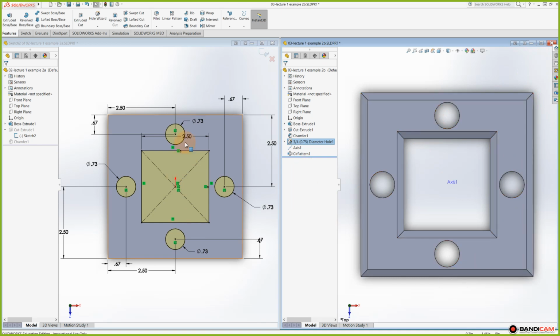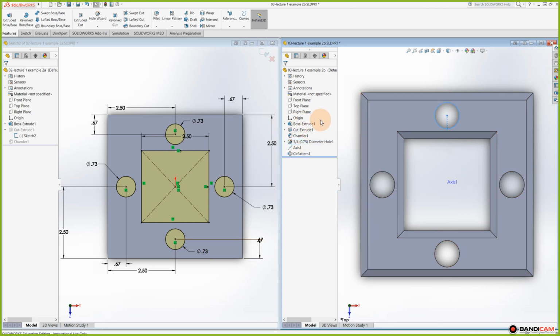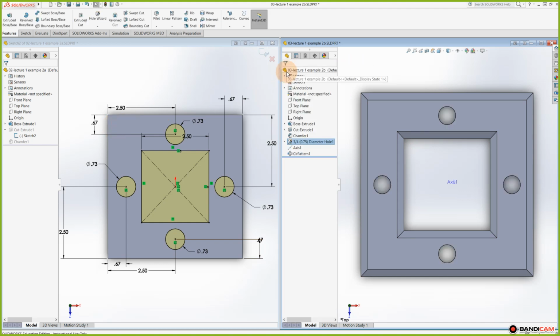In this case here, because I'm doing it based off speed, I'm going to purposely make them fast, and if I have to change them on this object, I will have to open this sketch, change this circle, change this one, and this one. Meanwhile, on the right, if I want a hole difference, let me go change this one, edit feature. All I have to do is change the size, so let's make it 0.5, a little smaller. I'm going to accept it, and like that, every hole is automatically updated.